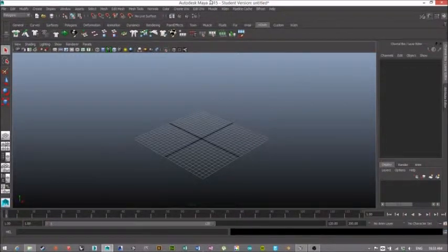You can take in your NURB surfaces and look at options with scaling 1D, scaling 2D, or scaling 3D, depending on what you want to do and how you want to do it. So there are ways to import meshes. Just a reminder, if you're moving from Rhino into Maya, meshes you import as an OBJ. If you're using NURB surfaces, you import NURBs as IGS. So when you're exporting out of Rhino, you export an IGS and you import the IGS into Maya.